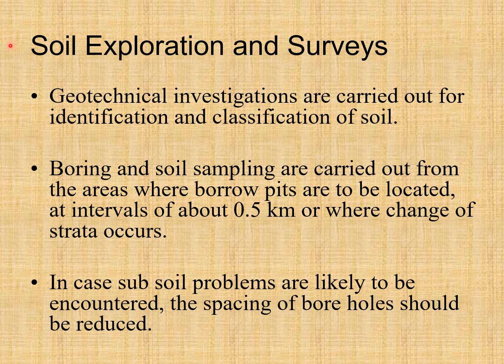Soil exploration and surveys. Geotechnical investigations are carried out for identification and classification of soil. Boring and soil sampling are carried out from the areas where borrow pits are to be located at intervals of about 0.5 km or where change of strata occurs.